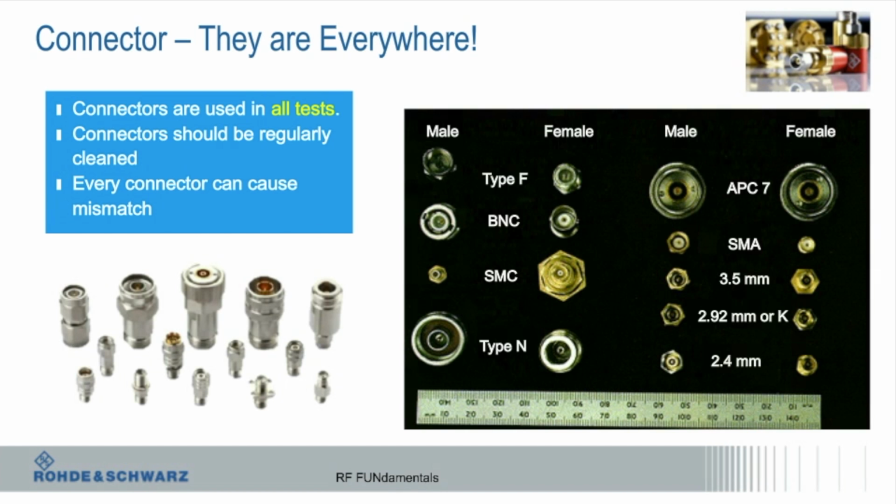Yeah, and that's a really great point. And it also leads me to a general comment with this stuff, particularly on a VNA: know what all your connections and cables are. Surprisingly, I worked with a guy, and some of these connectors are compatible with each other.